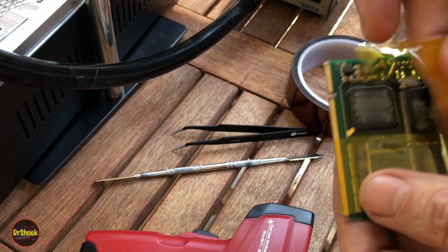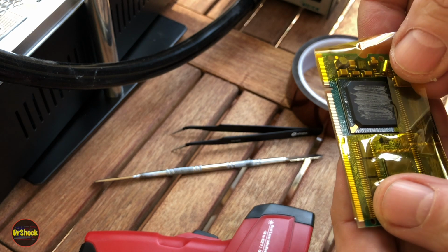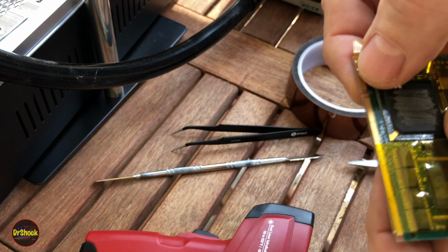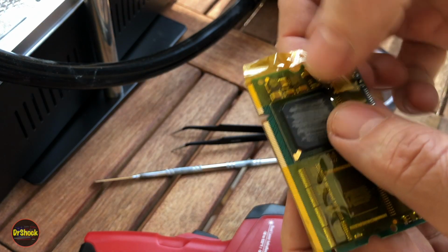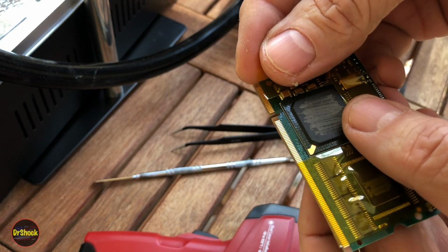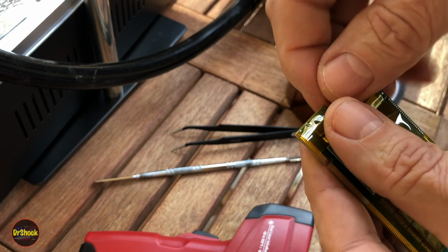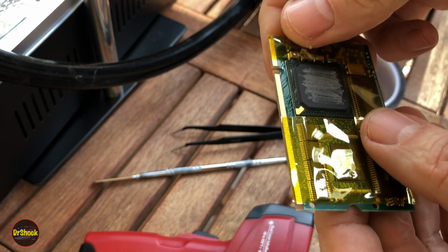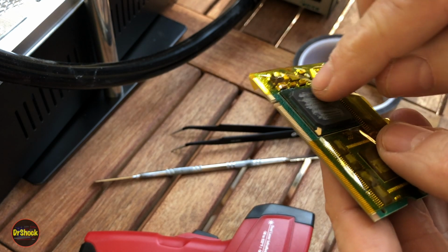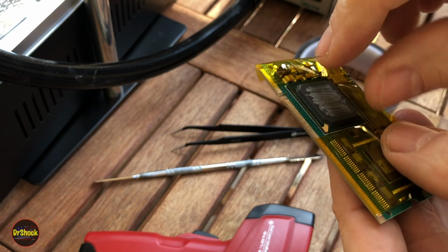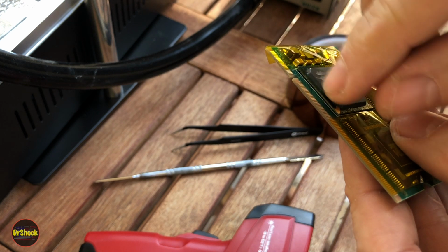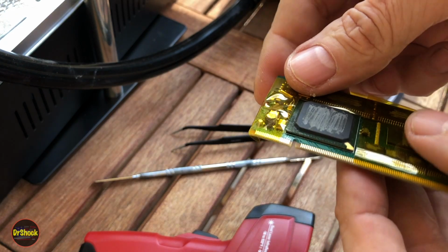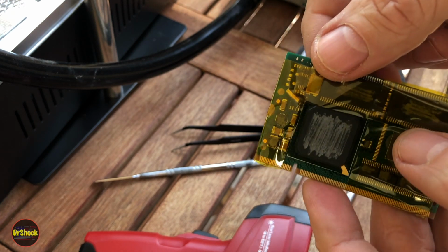Kind of prepping our board here. Just want to cover these other components with some Kapton tape just so they don't accidentally become desoldered during this repair process. So we're going to do a secondary reflow as the attempt we're going to make here, like we were saying earlier. It's not worth attempting to reball this guy, but if we can get all of the balls under here to liquefy, there's a possibility that any cracks in there could be repaired with this secondary reflow technique. It's just a kind of a last-ditch attempt given the cost factor of the device involved.